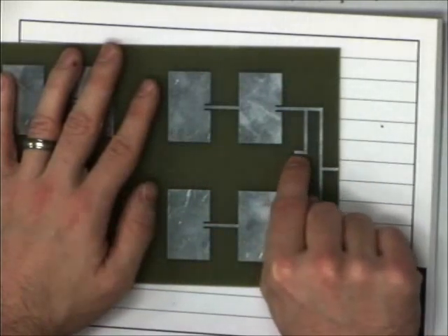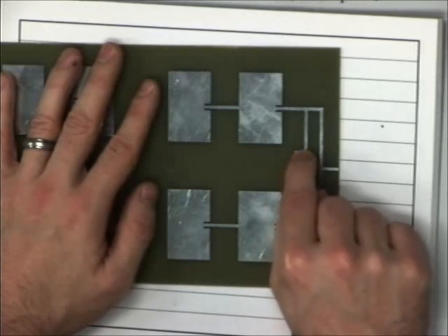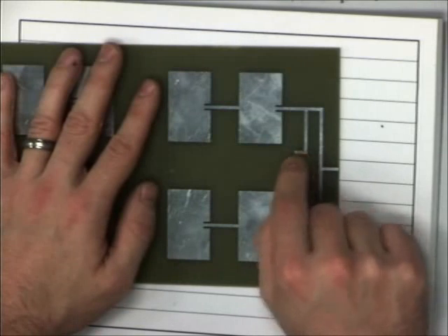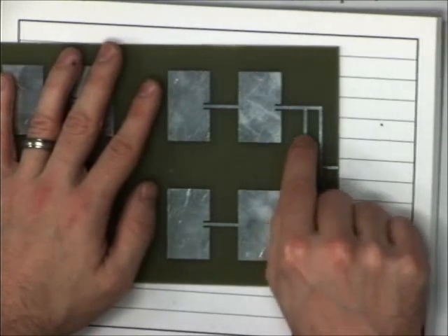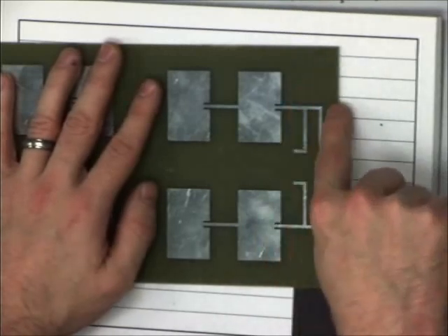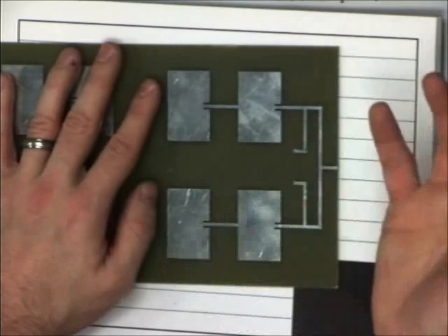As you move along, this stub looks to be probably a quarter wavelength or less at that frequency. What you'd find is that it started as an open circuit, but as you looked closer and closer along the terminal, it would be a smaller and smaller negative j something value, a capacitor.